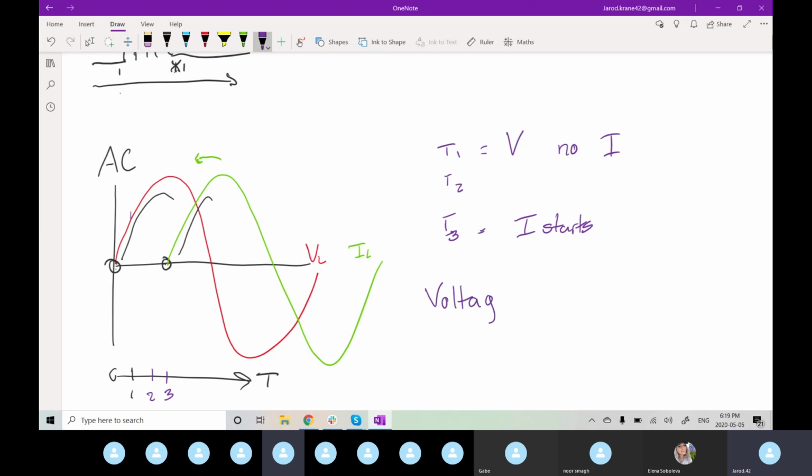So when you're designing a PCB, do you care about the phase difference when you're putting in capacitors and inductors? Like, why should we care? On our PCB level, we don't overly care, because with the values that we're dealing with, for one, this is for AC signals.